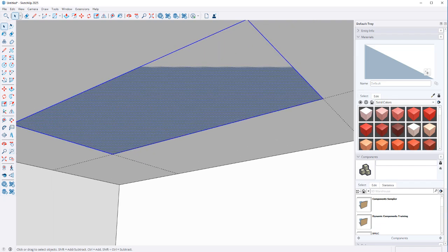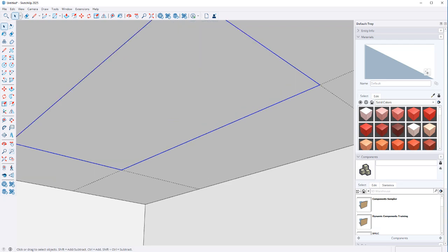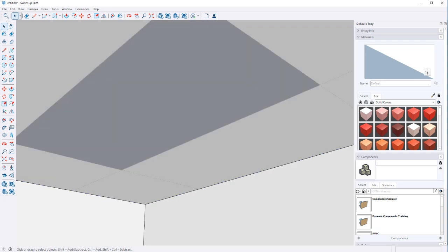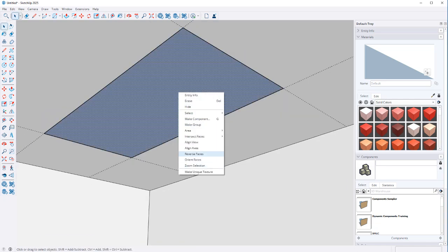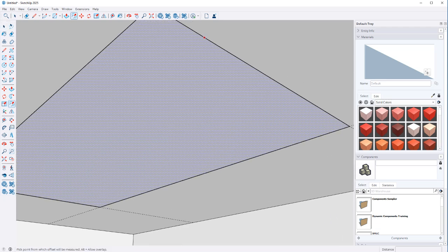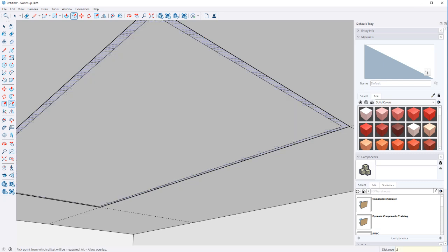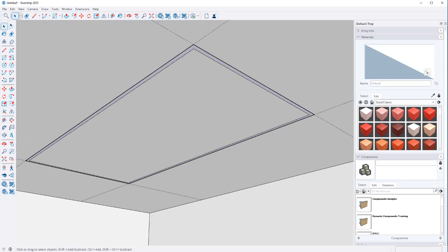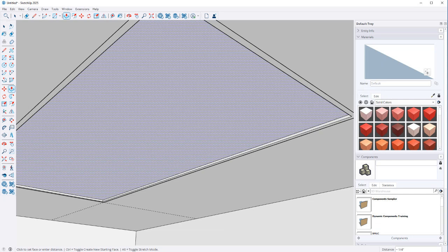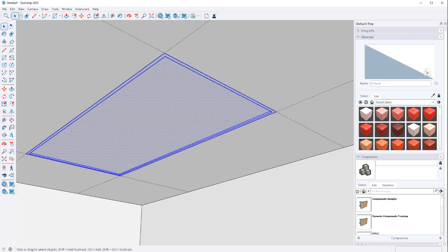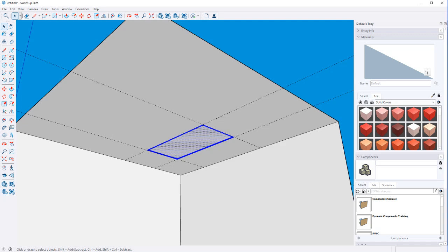That's probably a little bit simple for what we'd want to do. Depending on what exactly I was doing, I might come in and actually remove the background here so that we don't get that glitching behavior. And then with these lights, you typically have about a 1/2 inch offset like that, where there's actually a framing element going on. And then if you wanted to step it up a tiny bit, I'd probably recess this by a 1/4 inch. So 0.25. So that would be a fairly basic fluorescent light right there.